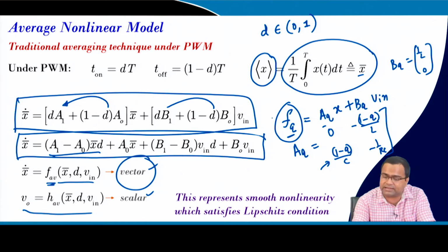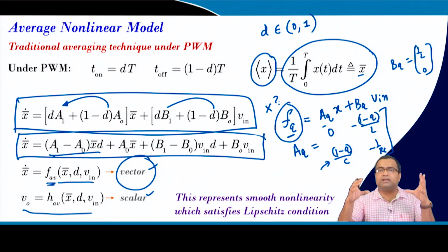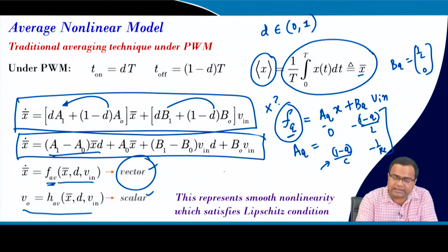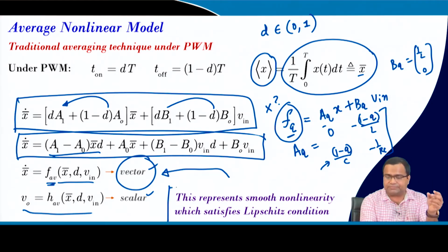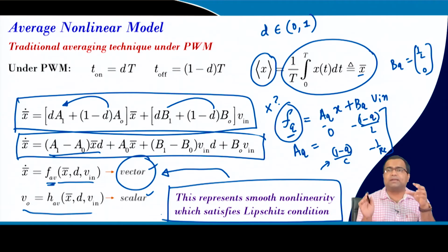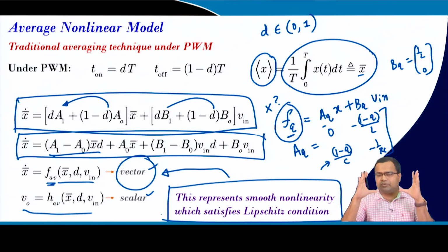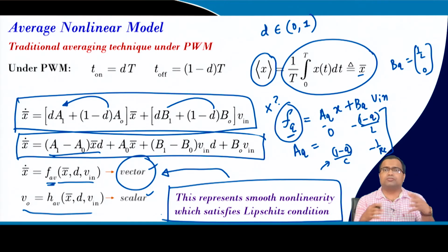We cannot apply Taylor series here because it is a non-smooth and discontinuous vector field due to the discontinuous control input, but when you apply the averaging technique, it becomes a continuously differentiable function, and then it satisfies the Lipschitz continuity where we can apply our traditional Taylor series or other control techniques where continuous or smooth vector fields are used.